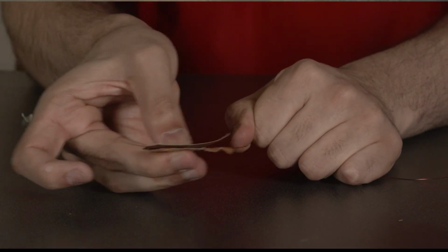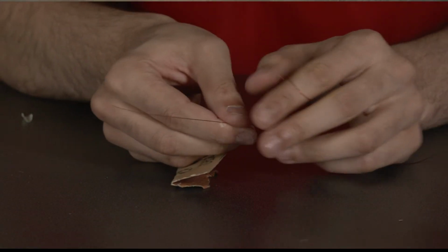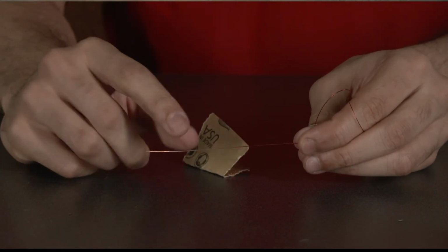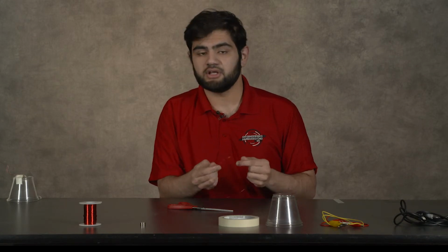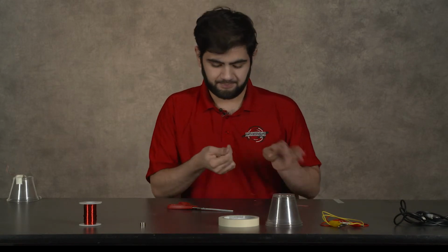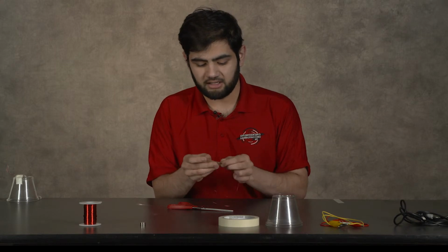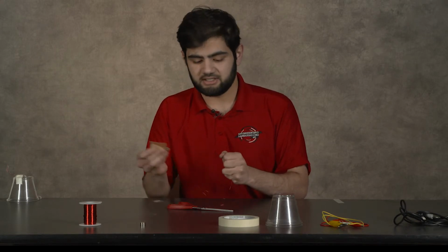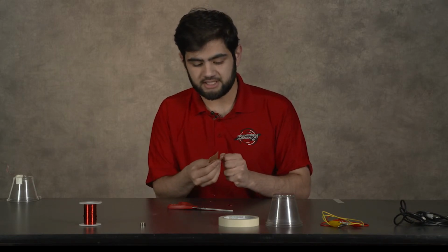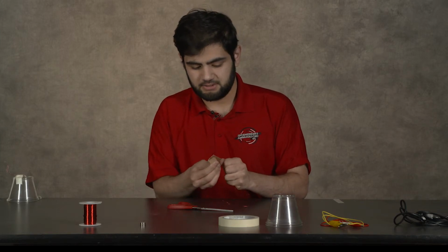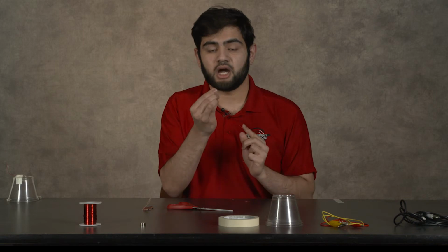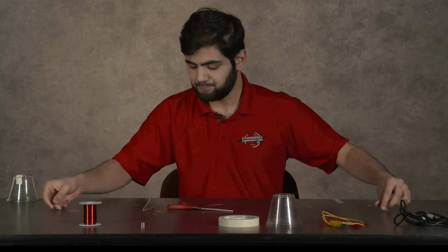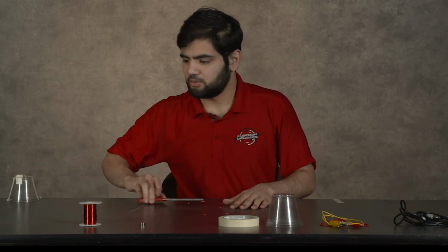insulation is removed, and you should be left with this shiny copper gold looking thing underneath. And so you want to make sure you're doing this on both sides, but not in the middle of it. The middle has to stay insulated. That's the only way we can get a good temporary magnet, is that the metal part actually isn't touching itself. So make sure you just have a decent area where it's copper exposed, and you're all good to go there. So you won't need these for a while.